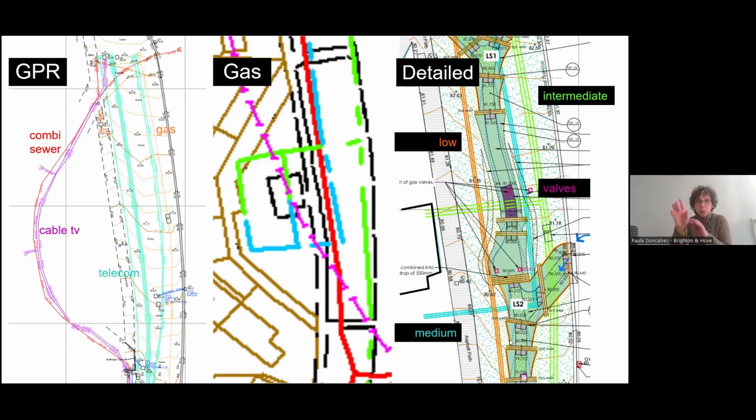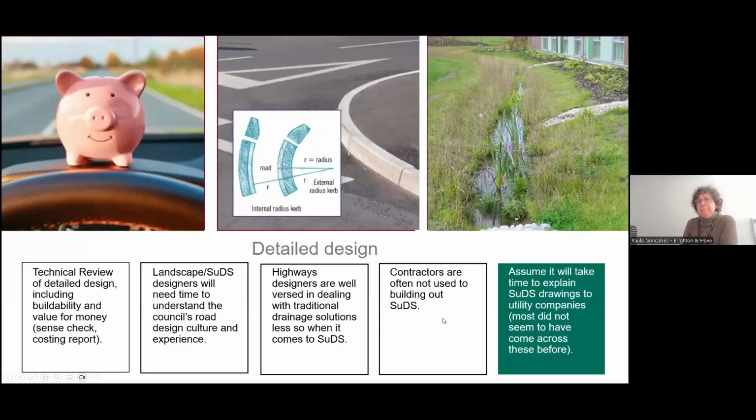The original design for this was quite different. This is the final design, and there were larger basins. But because of the services, you can then accommodate and design the SuDS around them. So that is a good thing. Yeah, I said, don't assume that the utilities know what SuDS are. In our case, the gas people had never seen a SuDS drawing. So that was a lot of conversation and bringing people around the table to explain. That will take quite a lot of time.